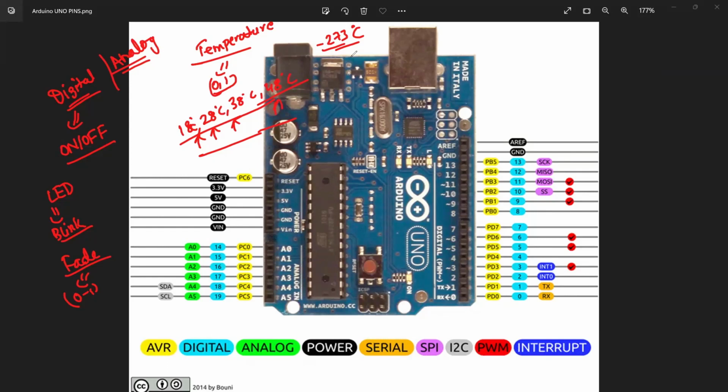Yes, sir, so the reset pin just refreshes the code? The reset pin is actually restarting the system. It restarts the system from point 0. So it will start reading the code from line 1, then execute the remaining portion of the code. This is the commonest thing we find in our electronic and programmable devices. The device will get stuck because of some power difference or something that happened in between. In that case, we hit the reset button and it resets the entire microcontroller, and the microcontroller will start reading the program from line 1 and execute the program completely.